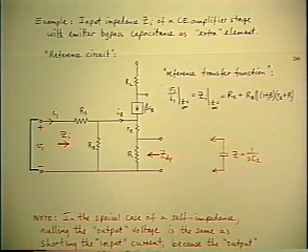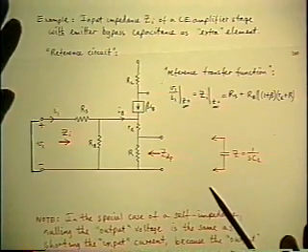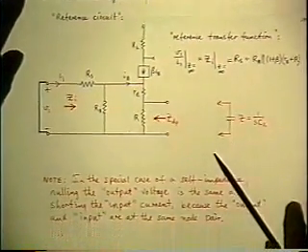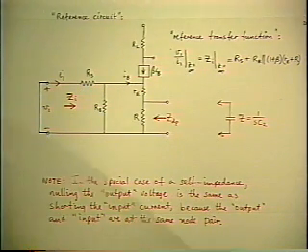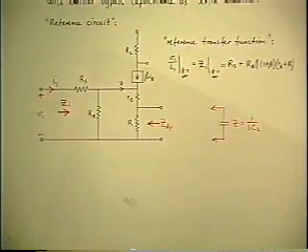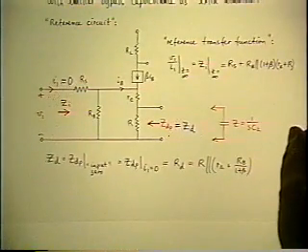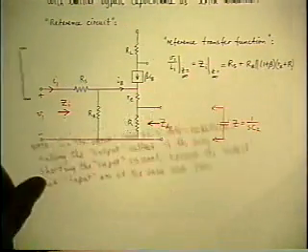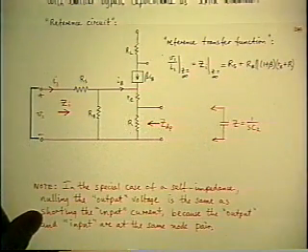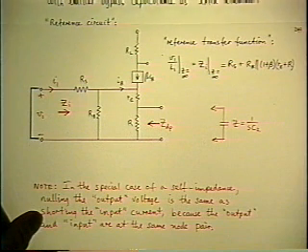And you don't have to invoke the null double injection condition. So that's a shortcut, because it's very easy to say those words. Let me do it again. To calculate ZD, you open the input, single injection. To calculate Zn, you short the input, single injection.